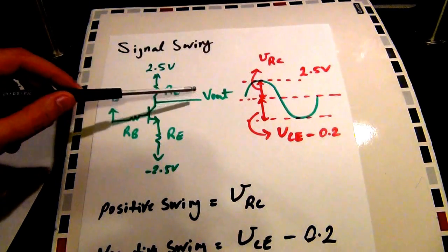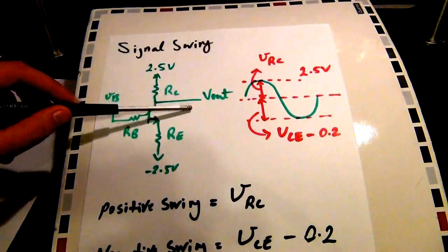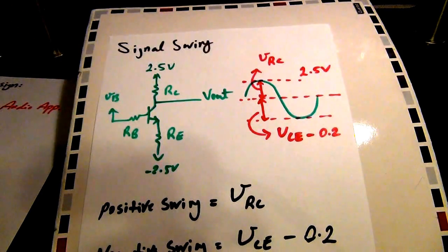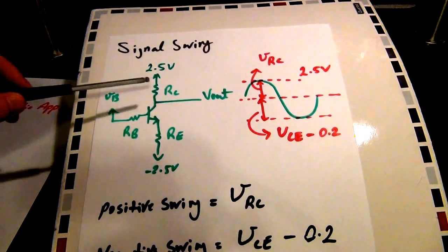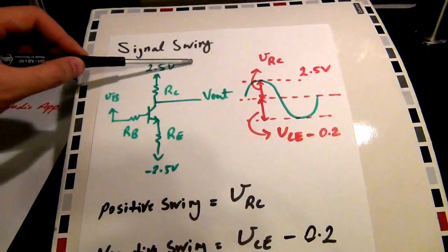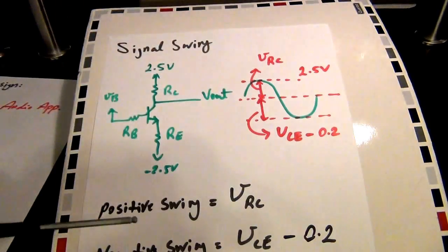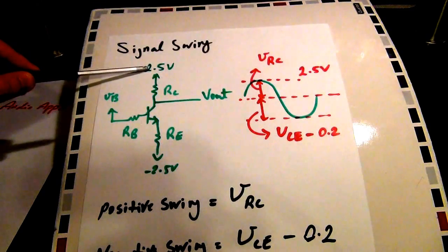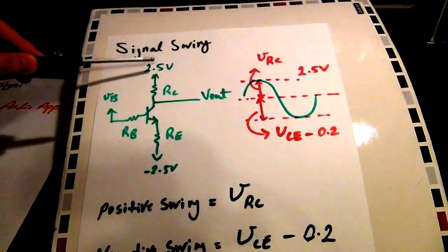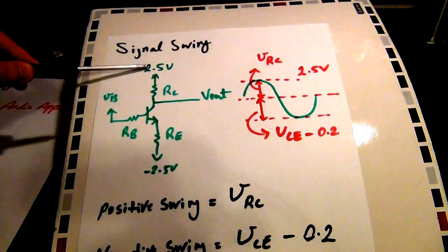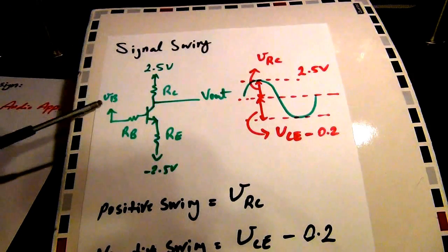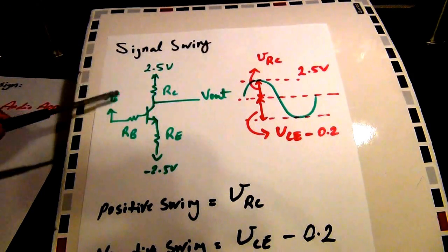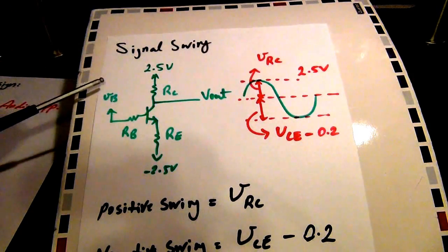Now let's see how the output signal swing will be affected by the way we distribute the voltage along these devices. The output voltage is going to swing up and down as I've shown here. The highest voltage it can reach is the positive power supply, because we cannot go over it. If this voltage reaches 2.5 volts, the device is already turned off because there will be no current through the device at all if the voltage across this resistor ends up being 0.